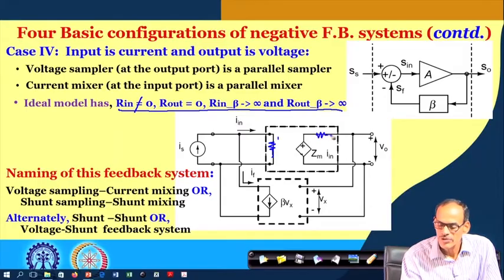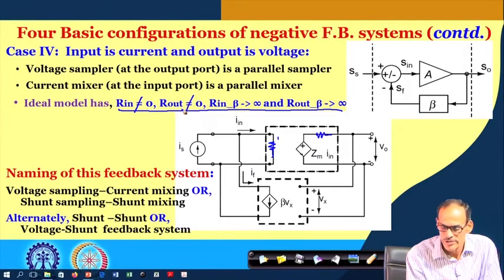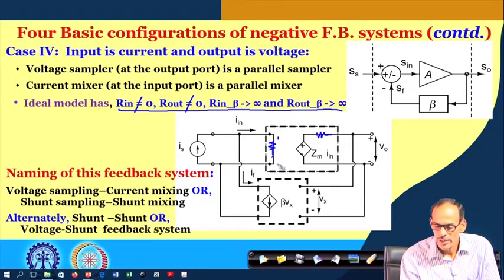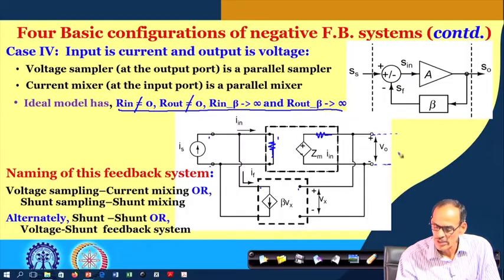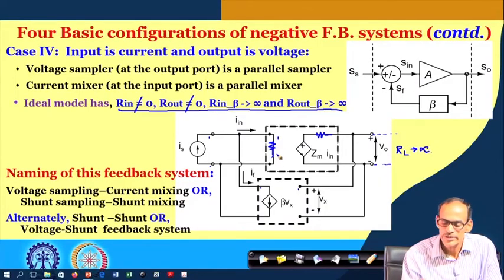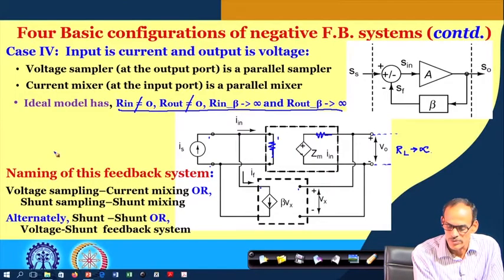Likewise, in case we do have output resistance which is non-zero, and still if I say that this is infinite and this resistance is 0, having 0 conductance. So, even in this situation, since we are not having any load here, we consider load resistance is infinite. So, even then in this case the loading effect is 0.